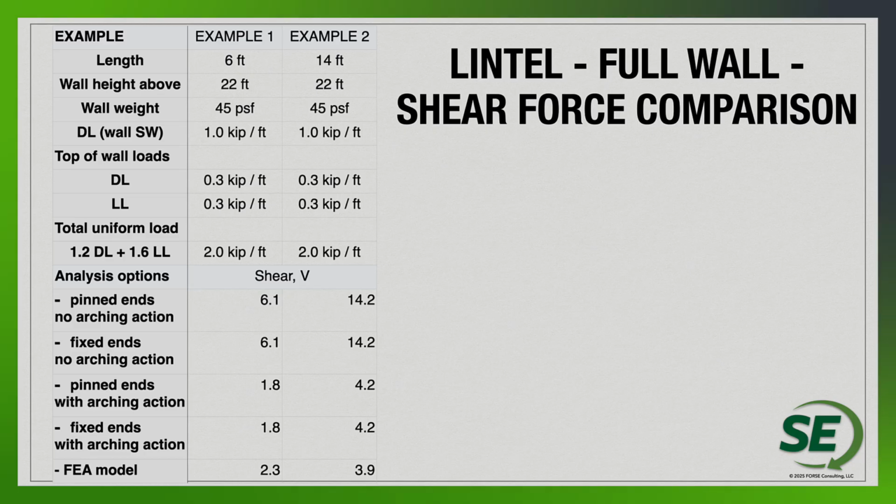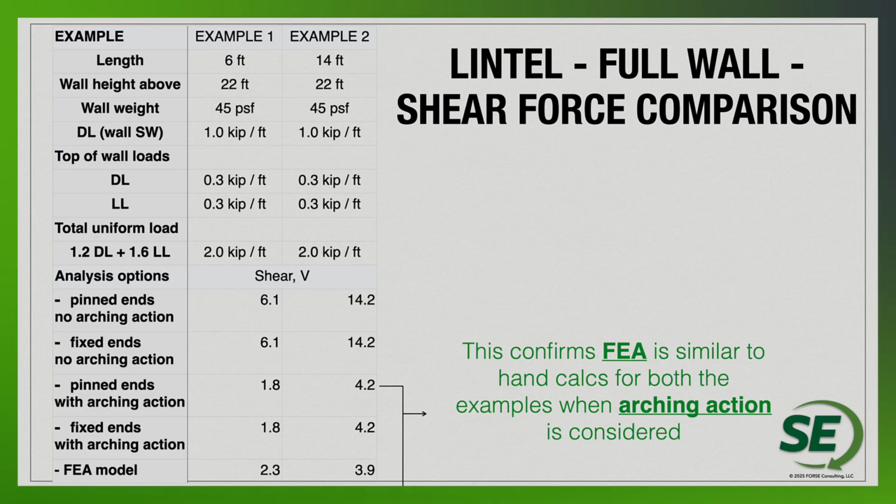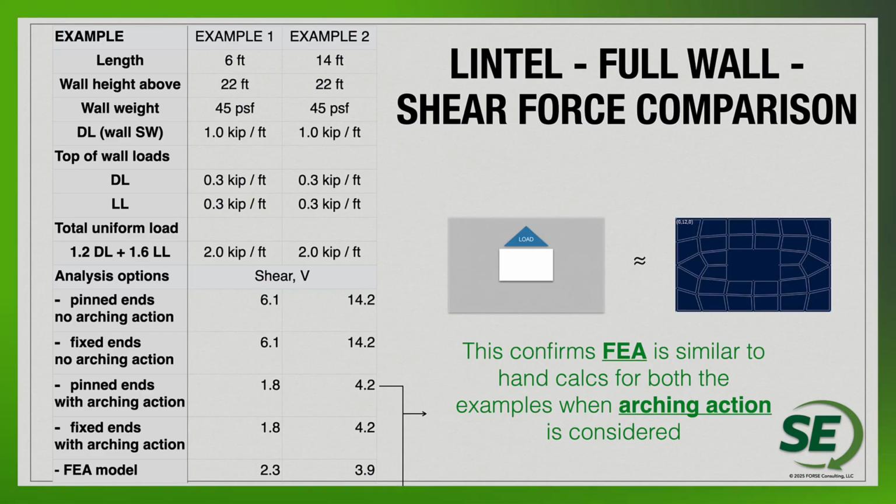We could see the actual arches forming within the plate elements based on looking at the contour maps. So again, you can see that kind of confirms arching action would be considered, even here, just looking at the shear force. Arching action is pretty similar to the finite element analysis that we're doing.